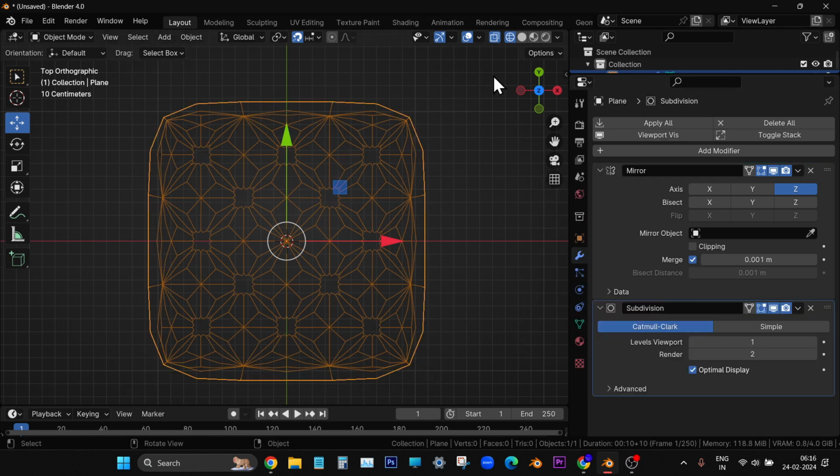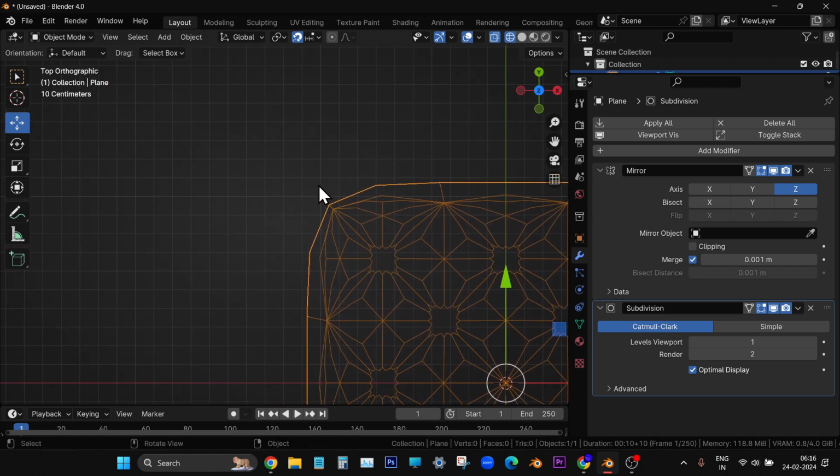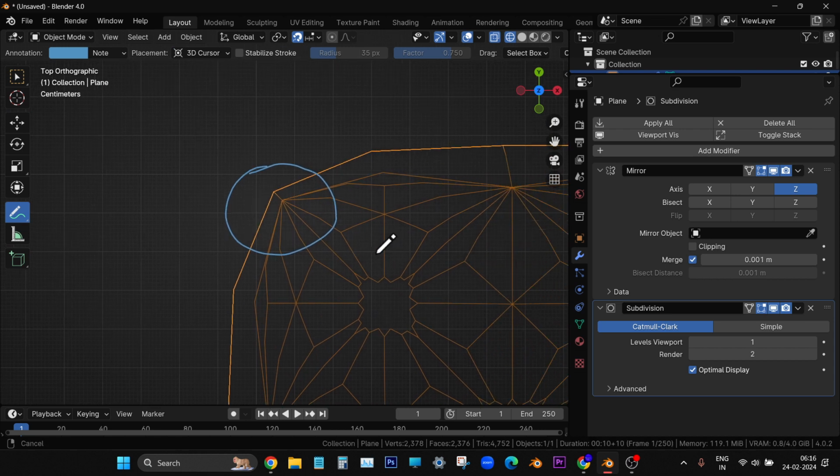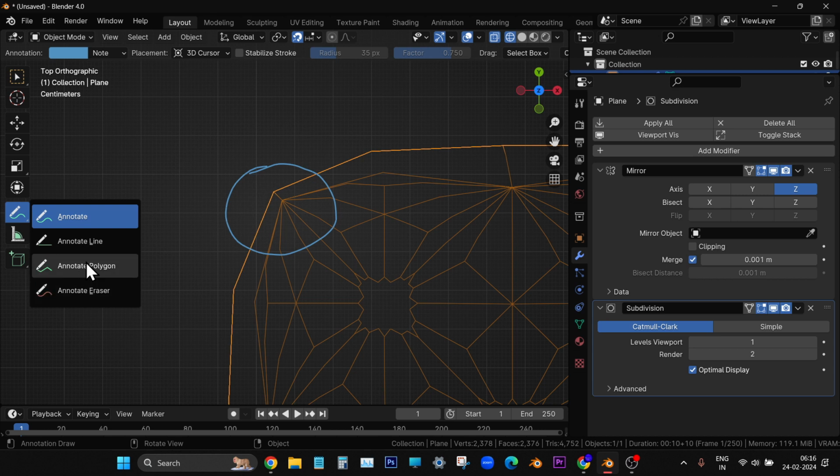Yeah, added. Now as usual we have to avoid this region, that is the mesh intersection. To avoid the mesh intersection we have to scale these boundary edges a little up to create a gap between this vertex and these boundary vertices, so that we won't have issues.